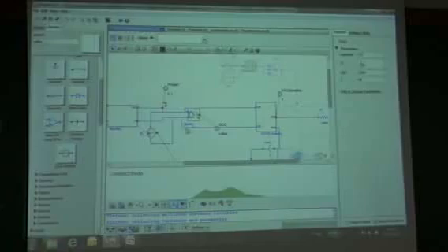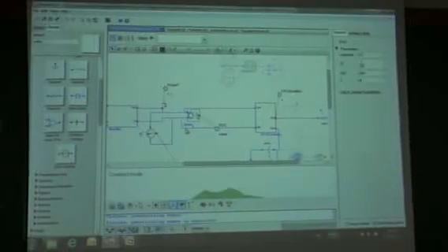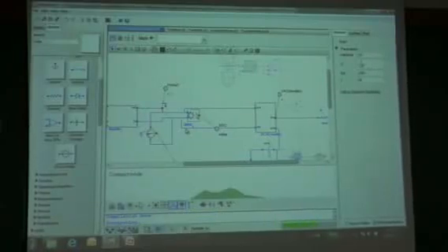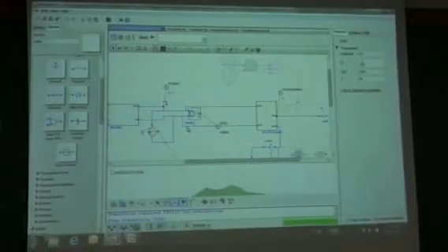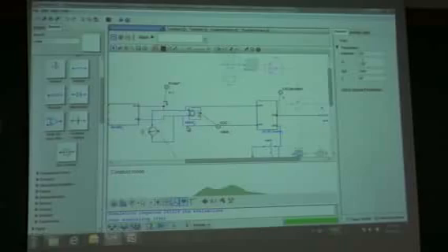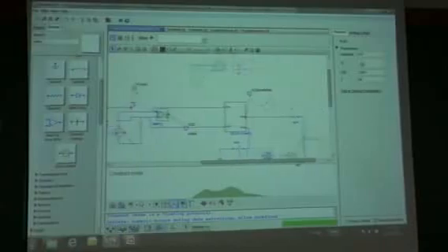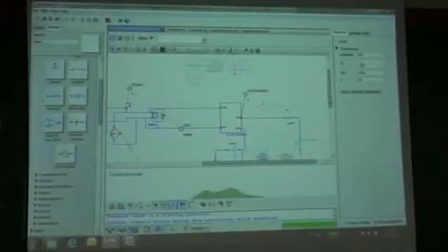Now, the main reason for the battery there is not just for energy storage. If you want to plug this into the main supply, then you have to reconstruct the main voltage signal to comply with the grid that you're going into. So it's 60 hertz or 50 hertz, or 120 volts or 420 volts, or whatever the grid requires. And then what we have at the end here is just some loading conditions that we were experimenting with.